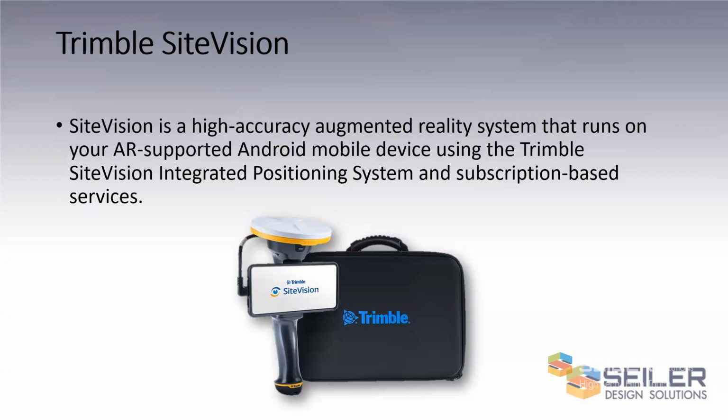It's a molded plastic handheld device mounted to a Trimble Catalyst antenna, which is a subscription-based positional antenna service. But this is a specialized firmware specifically for SiteVision. It's cable connected into the phone, where the phone runs an Android application that provides connection to online cloud services, position correction services, and then the unit itself also has a built-in laser EDM into the trigger, which is triggered by the phone via Bluetooth.